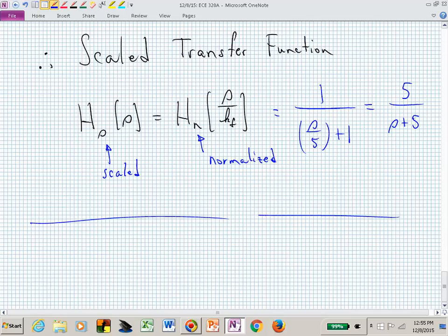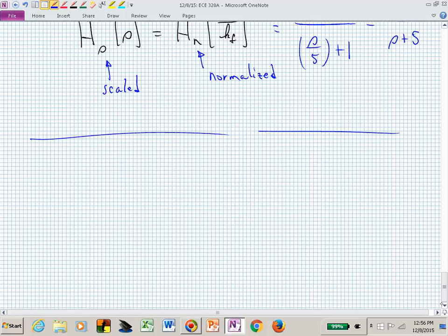They'll be on this circle of radius 1, all of our poles for a Butterworth filter. If we scale, we're just expanding that circle to a larger radius. But the angles separating all of those poles will be the same. That's where we're headed. Because right now, all we've done is looked at a first-order filter. Let's do more filtering.